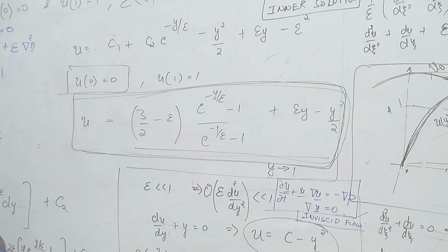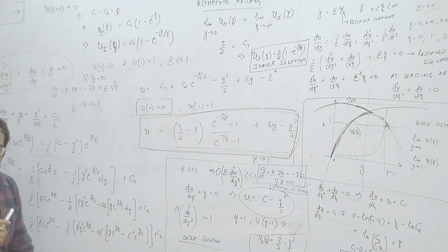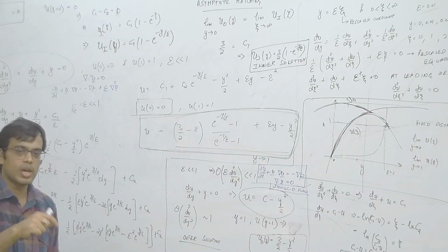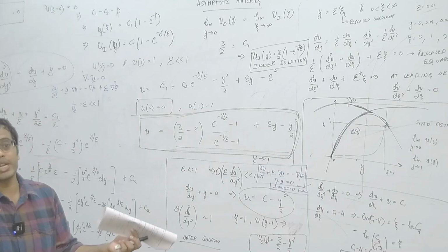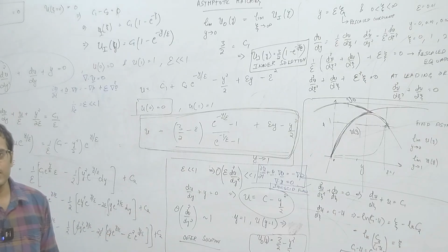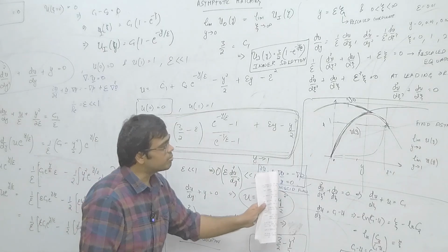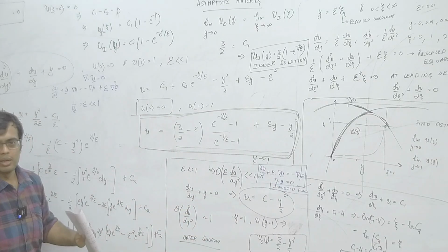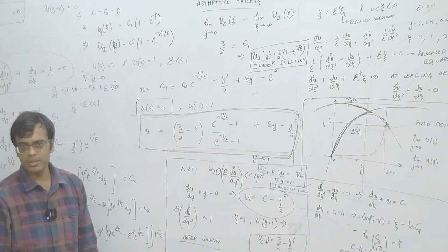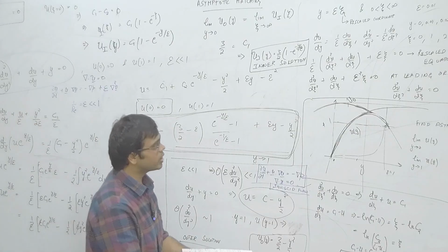Okay. And just because you have small viscosity doesn't mean you can approximate any flow to be inviscid. Remember, the dimensionless equations don't care about viscosity, they care about the Reynolds number. You could have small viscosity, but you could also have very small length scales, which makes the Reynolds number not so large. The idea is that in the limit of large Reynolds number, only the outer solution follows the inviscid flow equations. What does this outer solution mean?